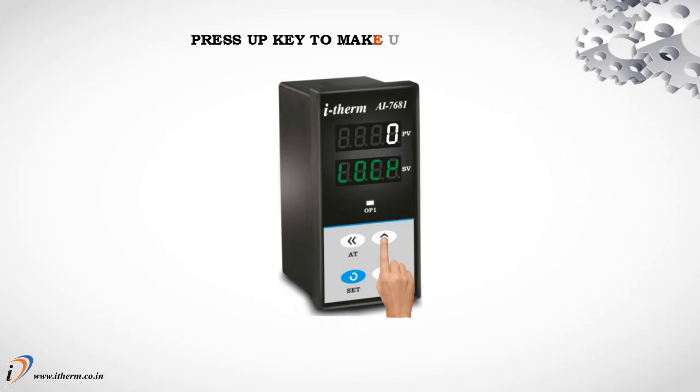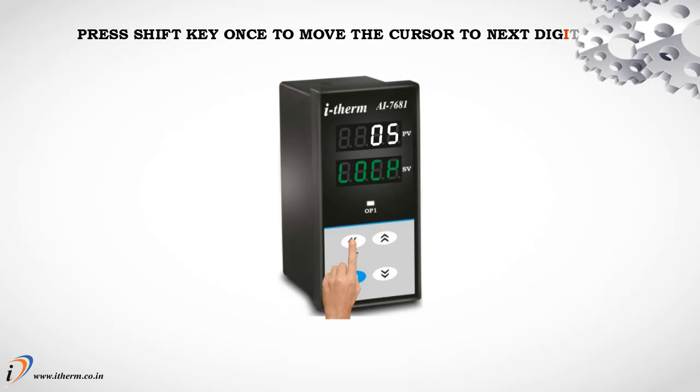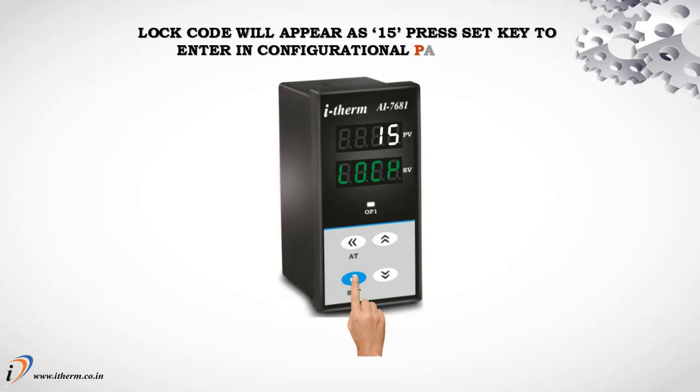Press up key to make unit digit 5. Press shift key once to move the cursor to next digit. Press up key to make unit digit 1. Lock code will appear as 15. Press set key to enter in configurational parameters.